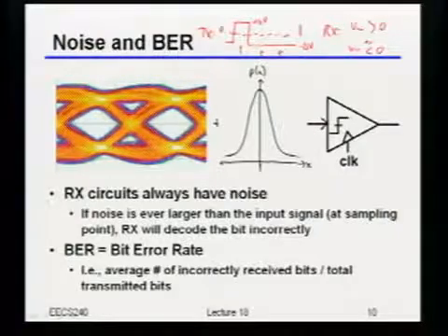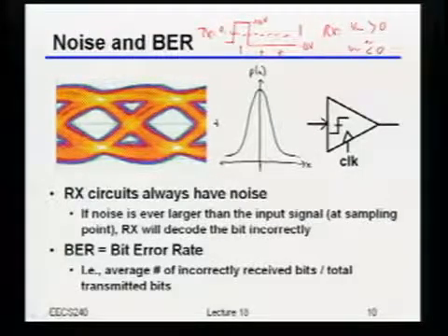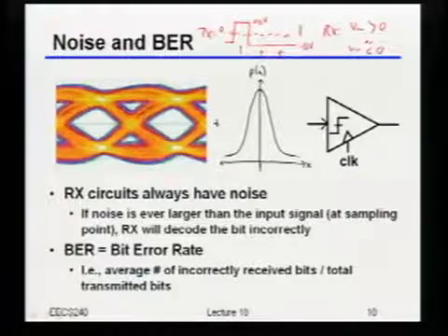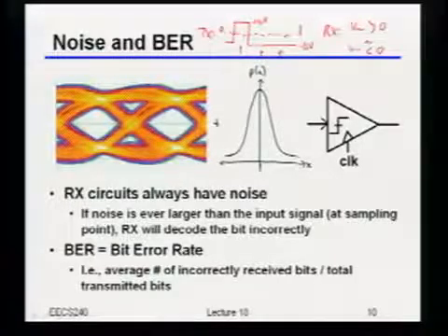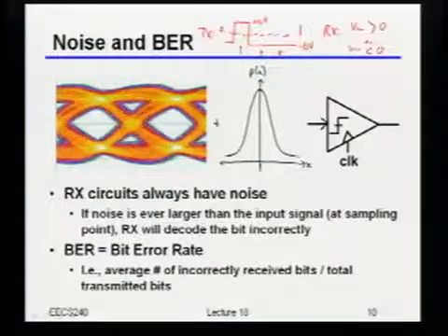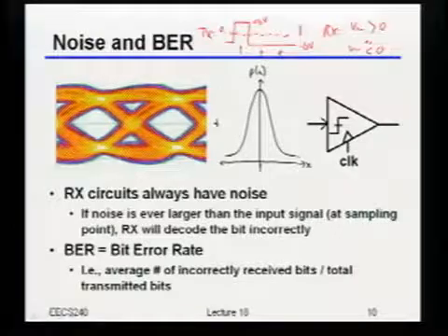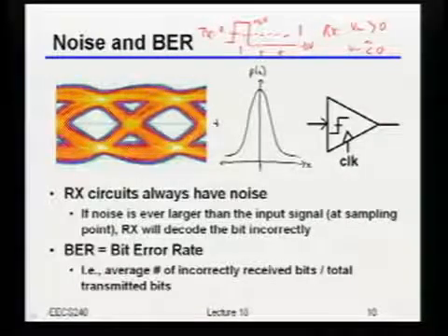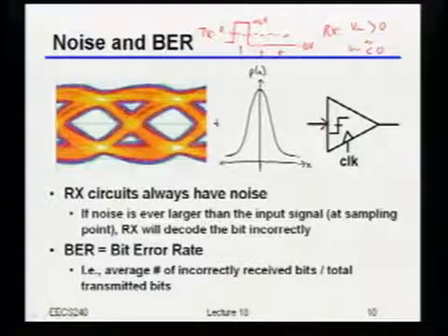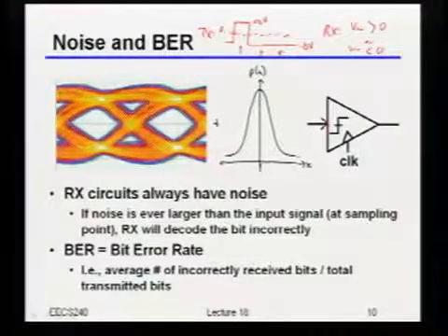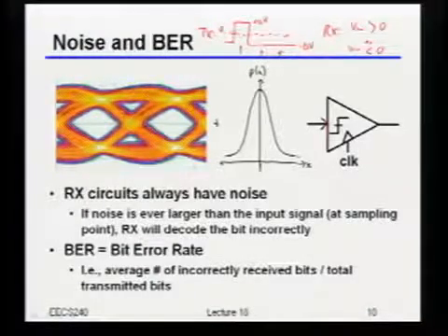So that's kind of like my ideal receiver, but unfortunately, no receiver is exactly ideal, okay? And there's really two things that can be messed up about that receiver. The first is perhaps the obvious one, which is that any circuit that I build inside of this has some noise in it. It's going to have some thermal noise.